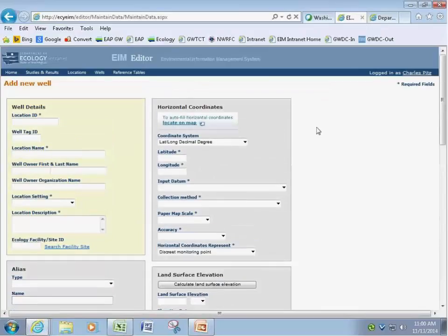However, if you don't have survey quality data, there aren't all that many options. In the old days, we used the USGS topo maps, and you could kind of interpolate between the two 40-foot contour lines and make a guess. And you could still do that. But there are better tools out there now to do this. And let me show you this one tool here.